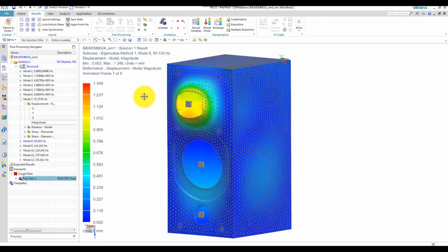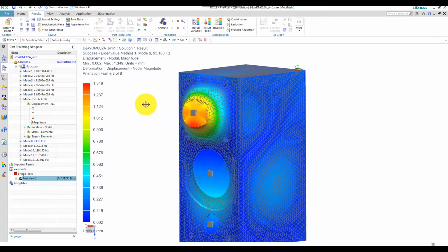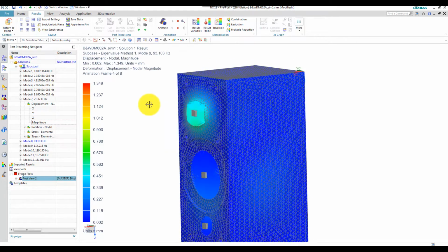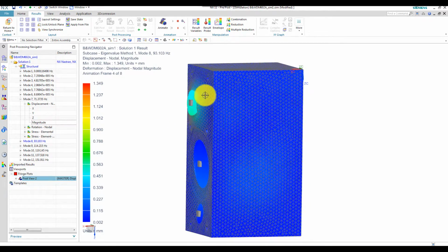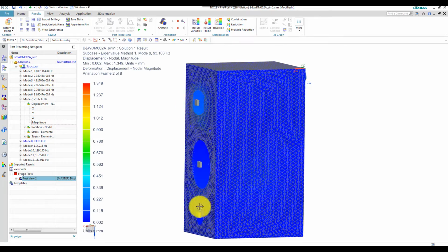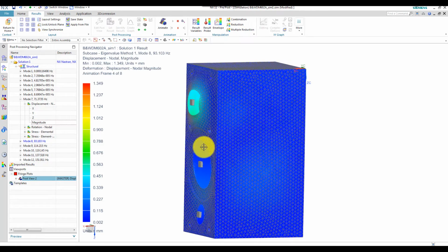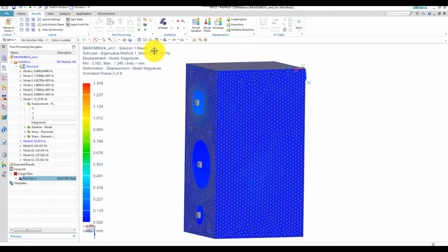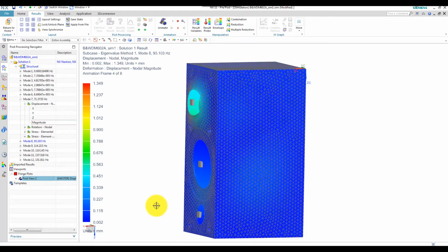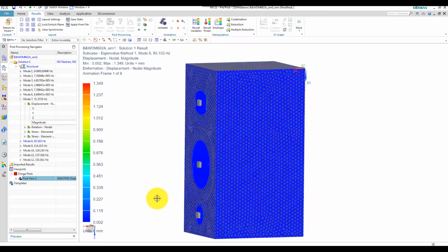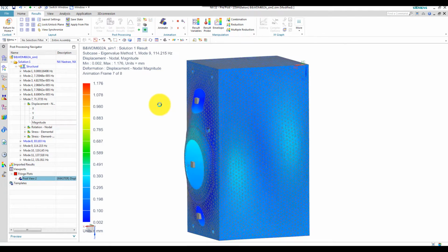It's mode number 8, and it has an eigenfrequency of 93 Hz, which is in between the E2 and the A2 string. And it's a quite local displacement around this tweeter. So it's mainly the front panel which has to be reinforced to increase this resonance frequency, the 93 Hz eigenfrequency. And then we should probably try to stiffen it so that it exceeds from 93 to above 110, which is the A2 string. Let's check the next mode.